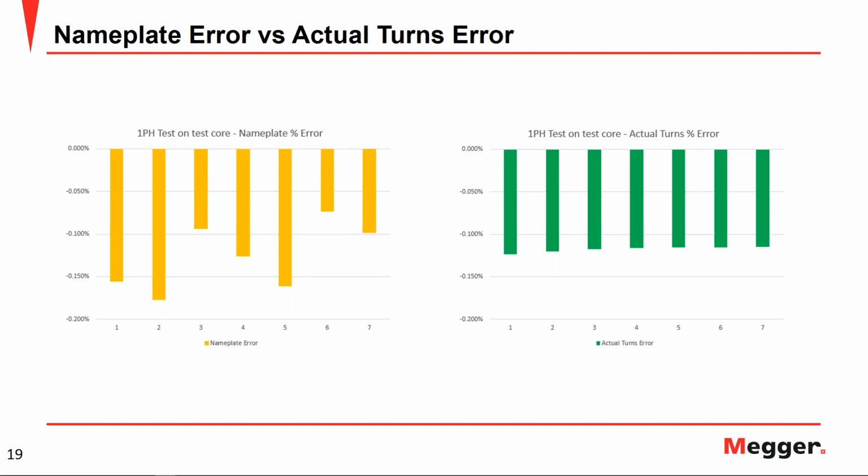So there's no compensation, just a measurement of all the different positions, and then you compare to the corresponding position from the voltage table on the nameplate, and then obviously you can calculate your errors for each of the positions of the tap changer.